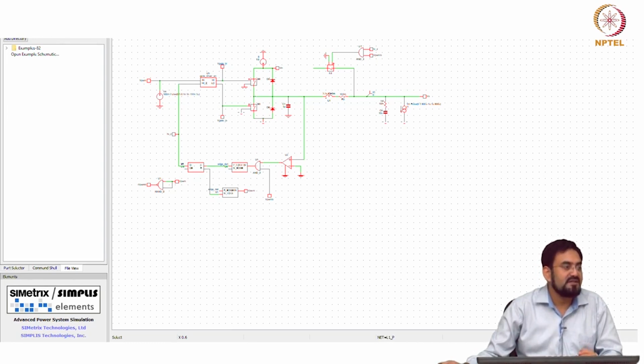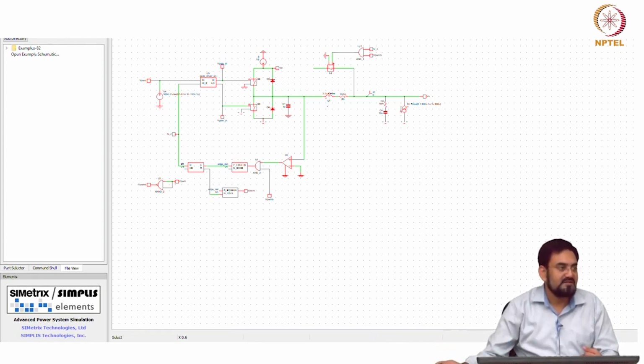The current will start flowing, but what will it do? You have an L and C network here. So any LC network will have a resonance. Okay. If you don't have this cap, then it will not resonate. But the moment you connect a capacitor with the inductor, it has to resonate. Okay, and we know that the DCR of this is not that high, so Q will be very high. So you will see a lot of ringing there. Okay, so that may cause some EMI issues.